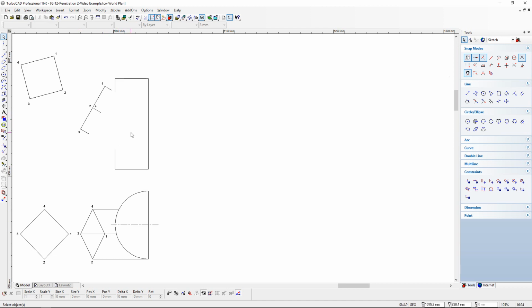on the front view. So when we start, we need to now draw a light construction line with intervals of 30 degrees onto the half cylinder so that we can see where we need extra intervals on the curve to be able to determine a proper curve on the front view of our penetration.